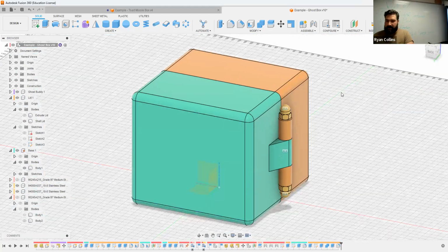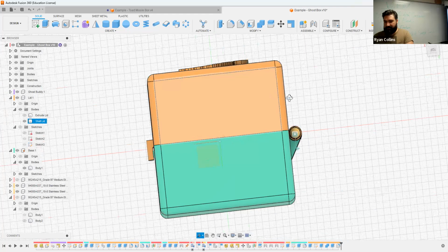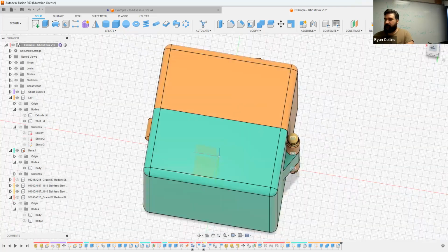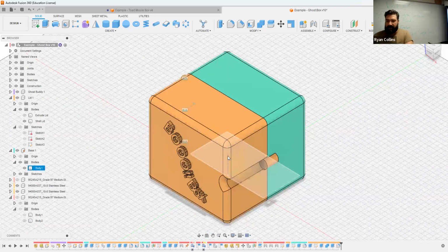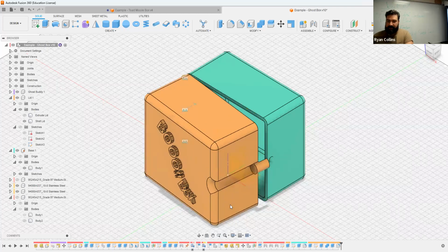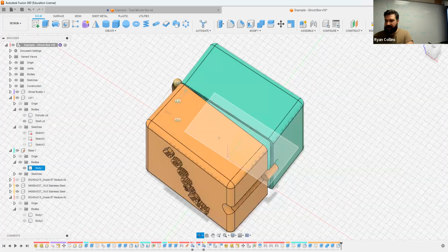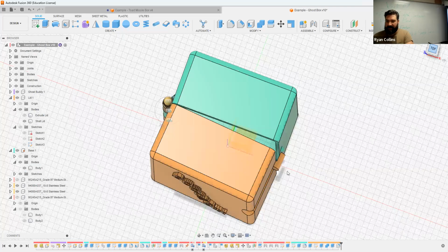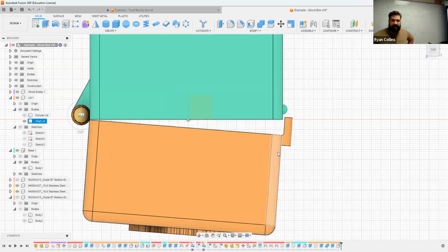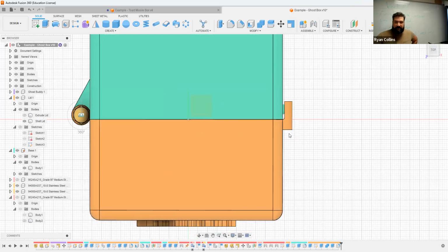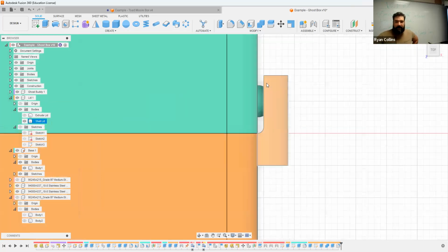Jeez. Of course, I still have to figure out and repair what happened there. So now when I go to open this, oh man, it is not letting me just select the whole top. Yes, it clips through, but should be enough clearance. But one quick thing, because I made that kind of long, doesn't hurt. Visually look, make sure that my tab's not going to interfere with anything else. No, looks good. So it's just going to kind of notch over that little bump, and that ought to work. Now, that's a pretty sharp curve. I would say definitely also put a fillet there as well.